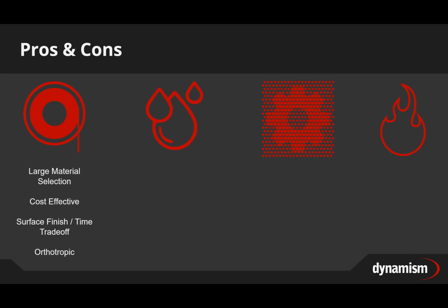With photopolymerization, you're going to get a smooth finish, almost injection molded quality. Very highly accurate and detailed. I think it's about 25 microns on the XY. Parts can be brittle though, and these materials are UV sensitive, so extended exposure to UV light will make them more brittle over time.